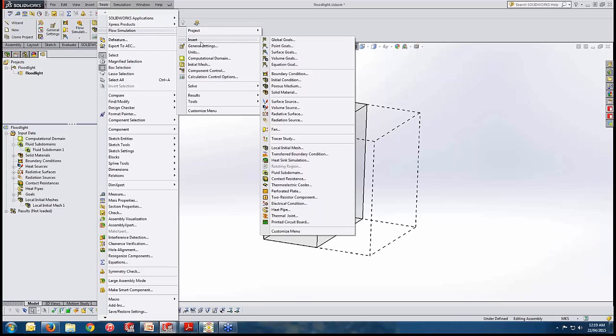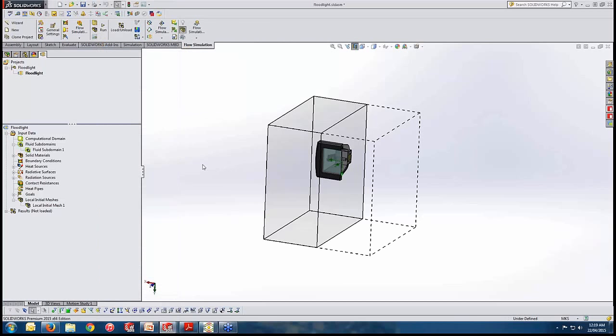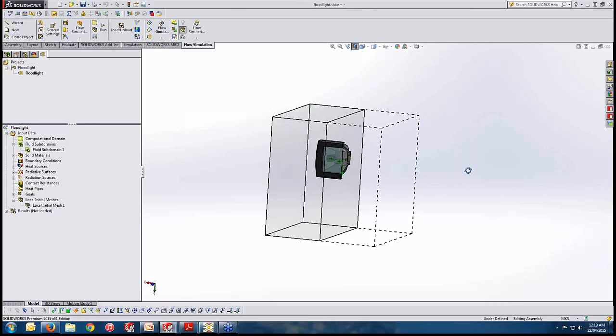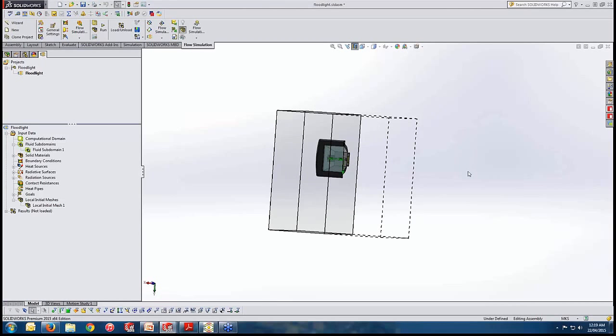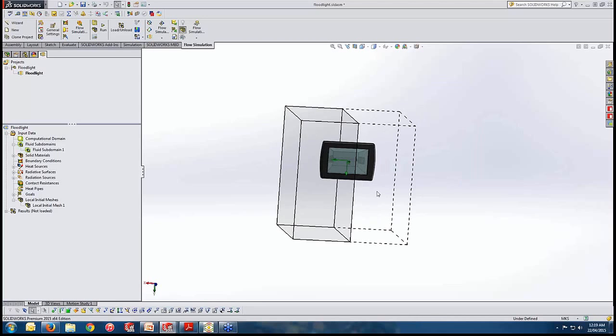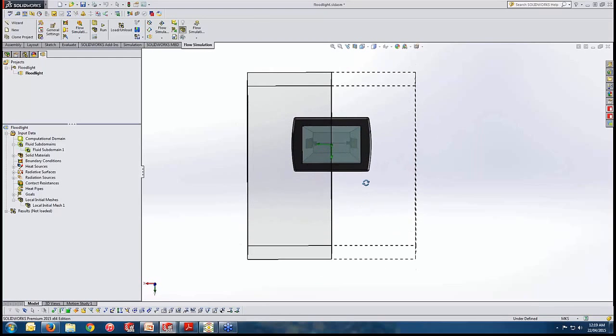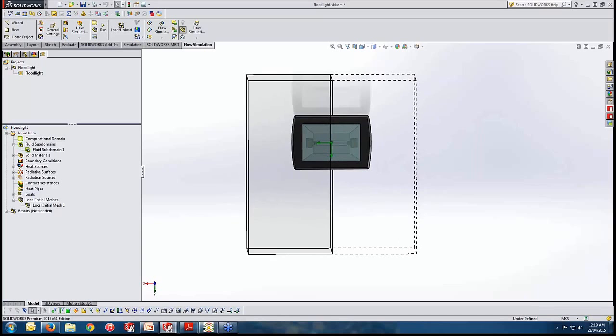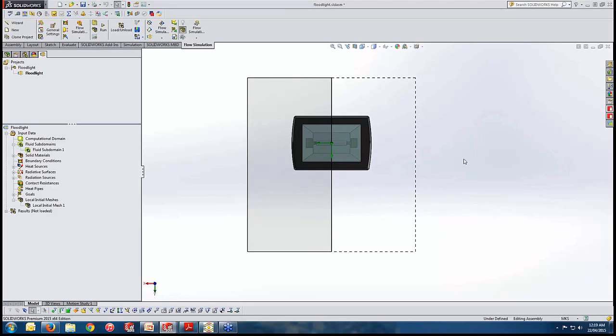Okay. The first step when you are trying to do a flow simulation in general is to decide about your computational domain, where the exact calculation are going to happen. So as we said, when we have a look to the model, there is a very good symmetrical sense we can simply predict and observe. Therefore, it is a very wise approach if we can get half of this model simulated and simply telling the software there is a symmetry line or symmetry plane in this model.